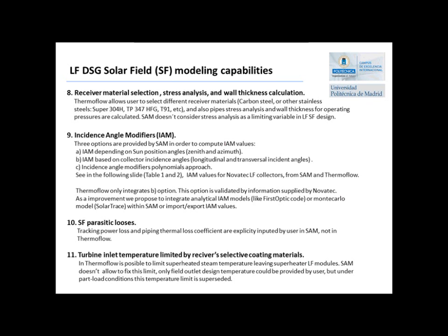As an improvement, we propose to integrate analytical IAM models like the FirstOptic code or the Monte Carlo model available in SolTrace software within SAM or Thermoflow. Solar field parasitic losses calculation. Tracking power losses and piping thermal loss coefficients are explicitly input by the user in SAM, not in Thermoflow.